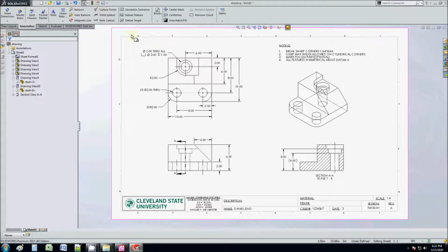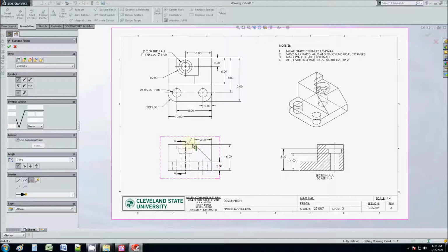Another thing you can do are surface finish symbols. So maybe you want to say, hey, what's the Ra of this? 0.6. Ra is kind of like the peak and valley average of a surface. But that's another thing you don't really define with the dimensions. I mean, you're saying, hey, these are the surfaces, but you don't say anything about the surface. Is it a mirror-like finish? Is it really granular, like a cast finish? So you can set these numbers. You can even say, what is the granular direction? Is it parallel? Is it crossed? Is it radial? You can set all these things.